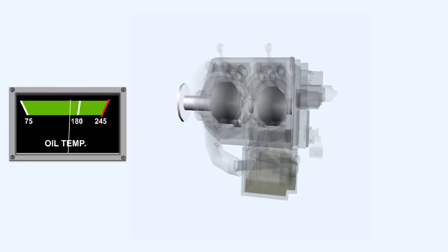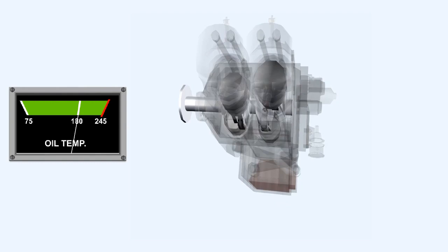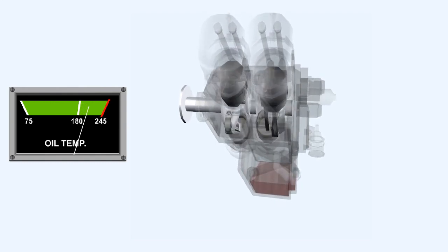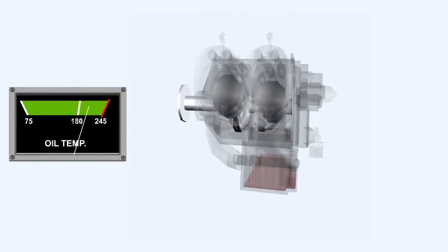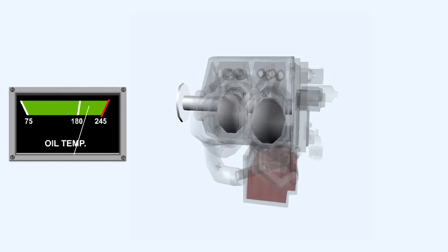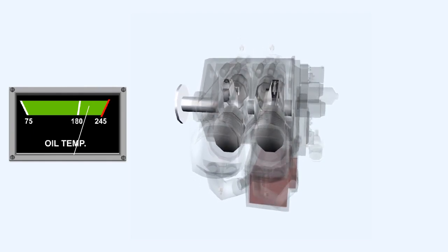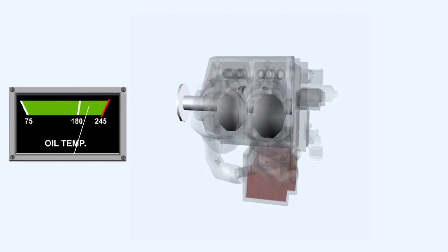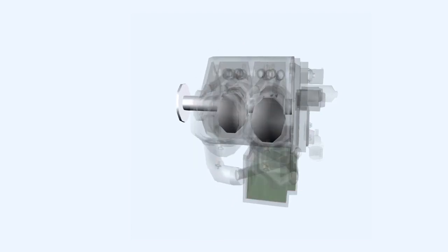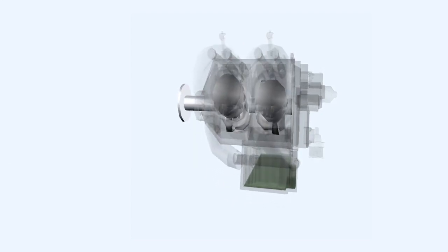Of the heat energy available in the fuel, up to 25% is wasted as cooling losses. Of this, up to 10% is removed from the engine by lubricating oil. As it's stored within the hot engine casing, the temperature of the oil is difficult to control. The oil becomes contaminated and oxidizes more easily because of the continual contact of the oil with the hot engine.